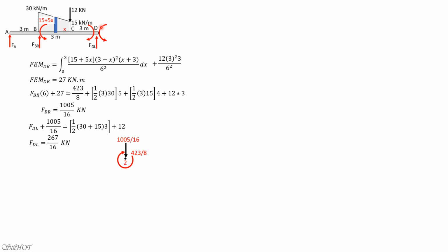So remember, there's moment here which is equal to 30, 15 times 2. So at node 4, at D, we have 27 minus 30, negative 3. So 3 clockwise. That's the only load because that's a support.